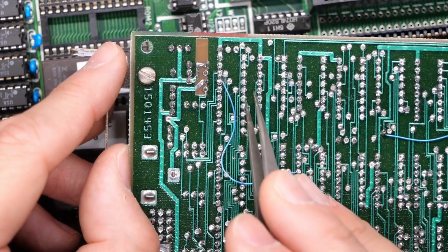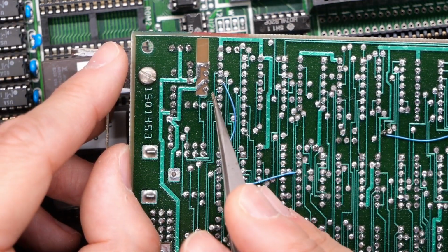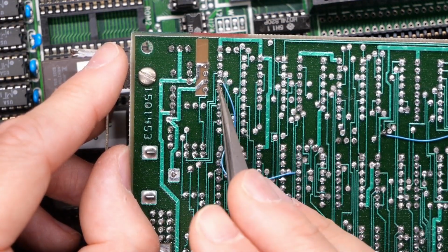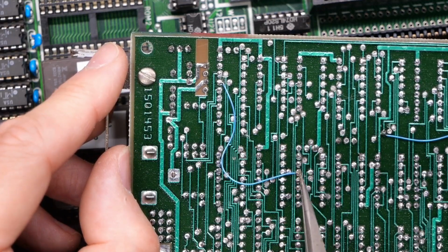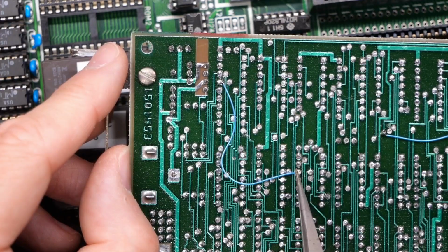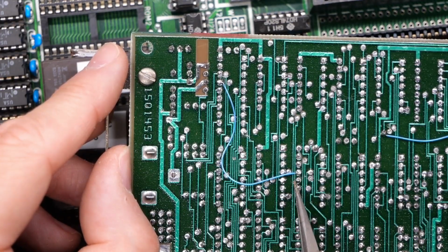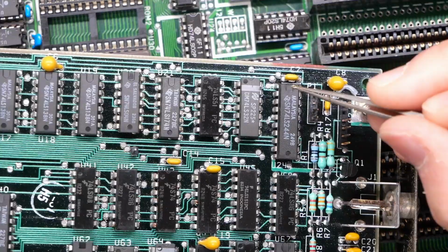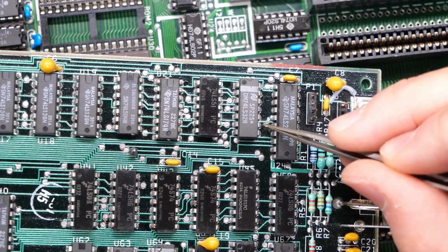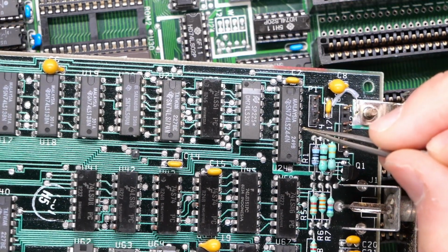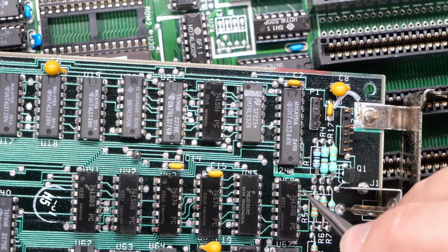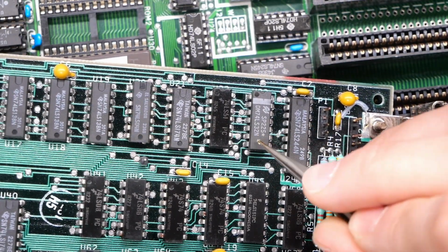And then the final mod we just did that does the speed up for the character printing routine is going from pin 17 on the LS244 here and goes down to here on this pin. So look for the vias right here that are like that. You go to that pin, that is that 3.57 megahertz that I'm picking up. Before you do that though, and this is on U24, the LS244, you have to cut the trace that is normally feeding that pin on pin 17. And that is that right there. So I just cut through there, and now that disconnects whatever pin 17 was originally connected to.